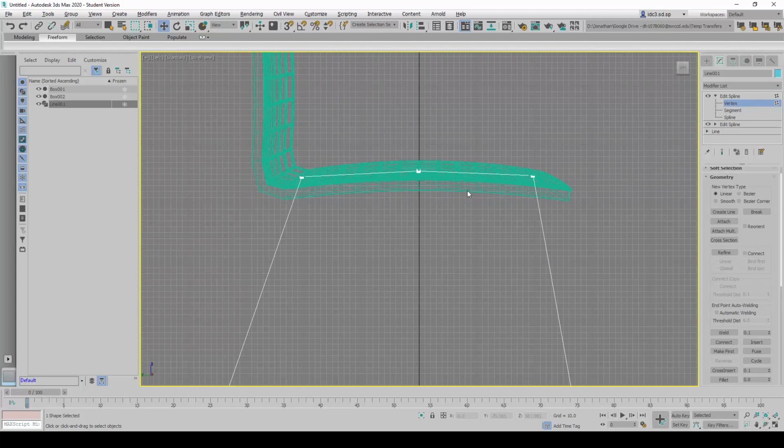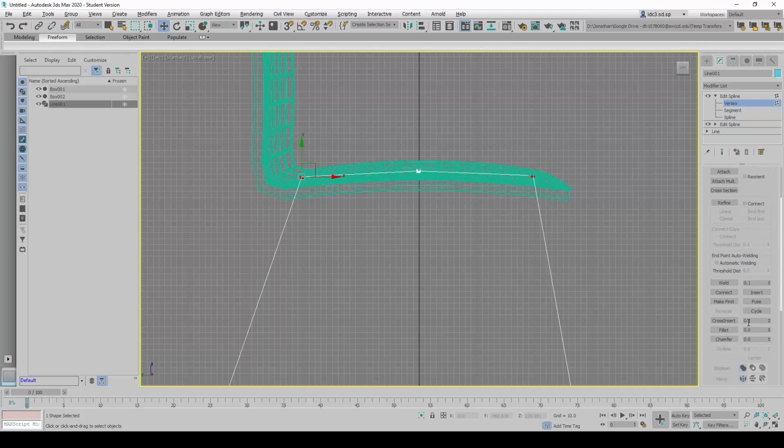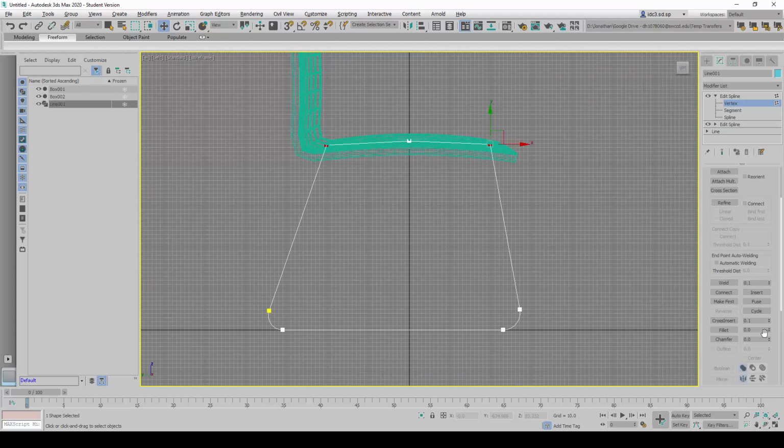With this now, at this stage, I will select the two vertex points here and work on my fillet, so that I can still retain the slight little curvature down here. I'm just going to look at this and study what kind of curvature will look good. I think 35 looks quite nice, so I'm just going to change this one to 35 here, this way.